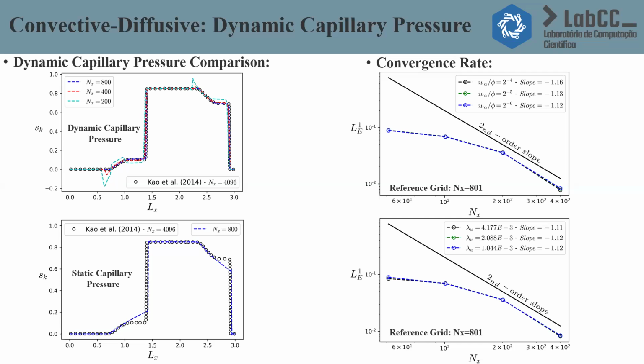I did the same for the diffusive convergence rate, fixing the diffusive term. In this case, when I take into account all the points, I have a slope of approximately 1.1 or 1.2 maybe. We can see that the convergence rate increased a little bit when I take into account point by point, but it's not so relevant when I have a limit of mesh to perform it.